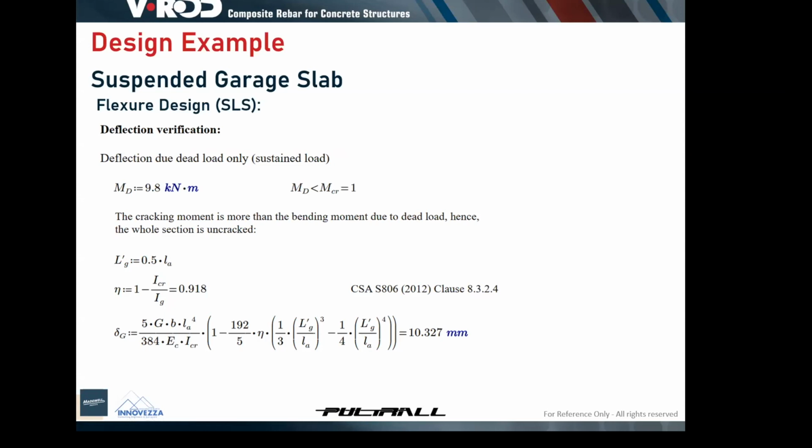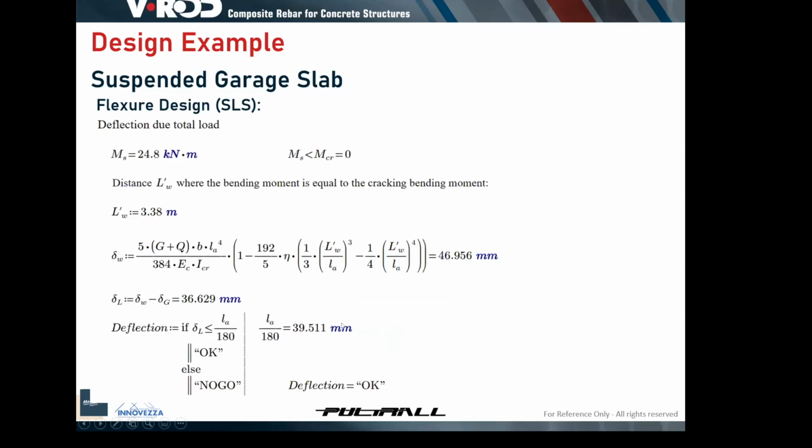Deflection: because it's a suspended slab, we had to calculate the short-term and the long-term deflection. We first calculated the deflection per the dead load only, 10 millimeter. Then the live load, about 36 millimeter, which is lower than the requirement of 39 millimeter.